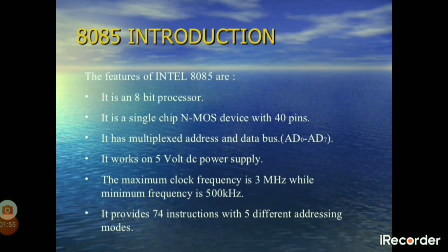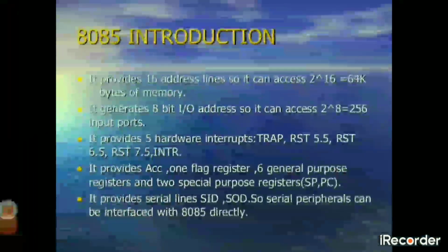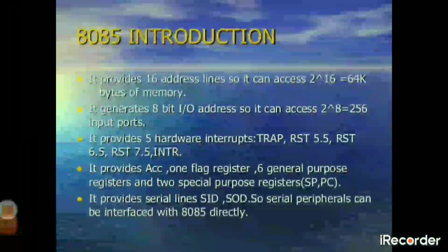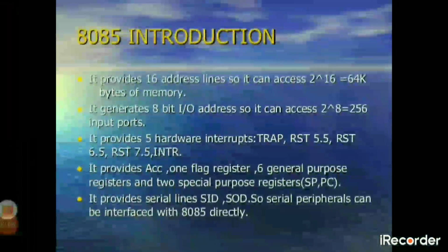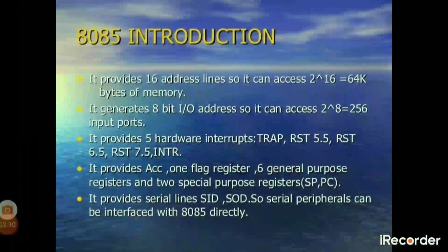It provides 74 instructions with 5 different addressing modes. It provides 16 address lines, so it can access 2 to the power of 16, that is 64 kilobytes of memory. It generates 8-bit input-output address, so it can access 2 to the power of 8, that is 256 input ports.